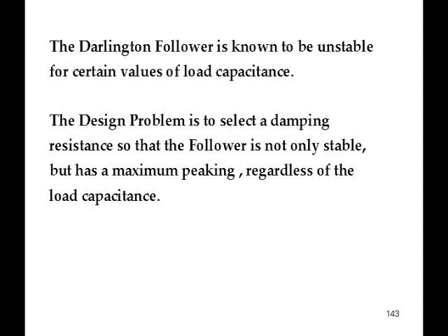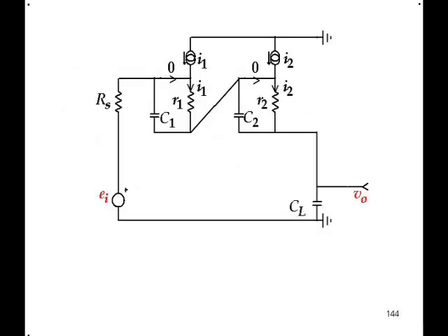Here's the linear model. Cascaded emitter or source followers. This time the C1 and C2 represent the basic charge control capacitors, which I didn't put into the previous example, but I could have done. The simulator will handle any number of those, of course. And to make it easy, I've assumed that we have FETs, not BJTs, so the gate current is 0 in both cases. Alpha is 1.